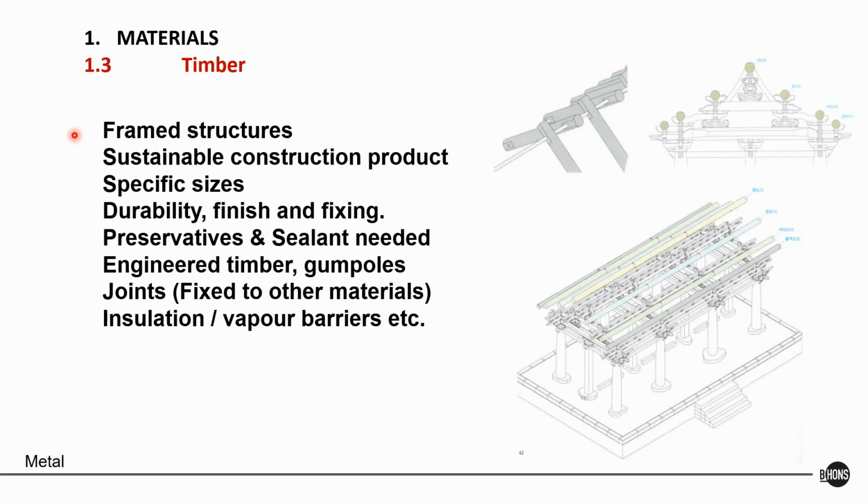So you can go and cut timber, but if you're designing something that's 110 mils or 108, it means every single plank needs to be cut by 6 millimeters, because the designer only allowed for 106 mils. You've got to think carefully. Why do you choose that size and not simply use the industrial size that's available at the moment?